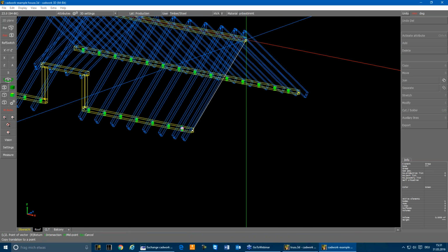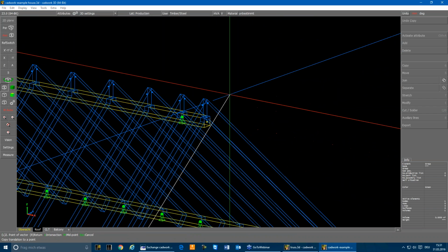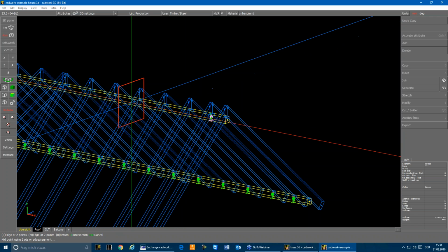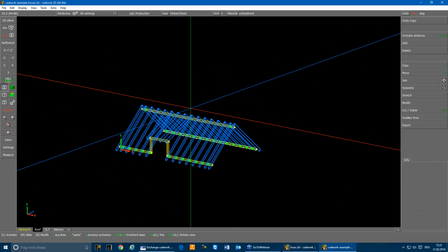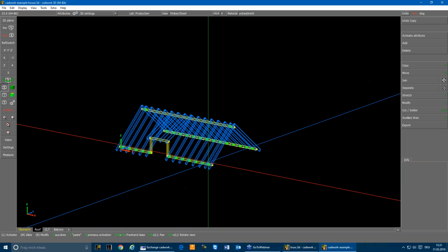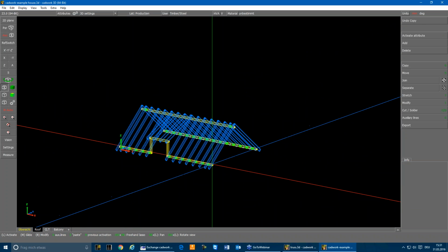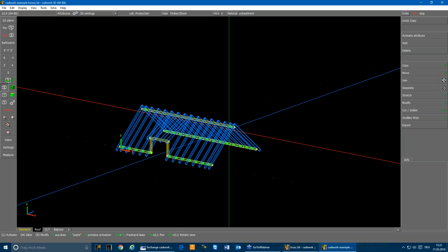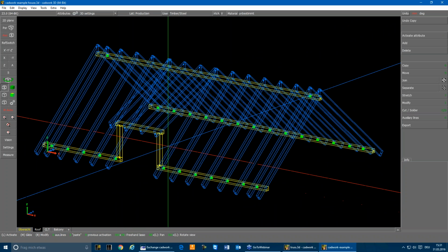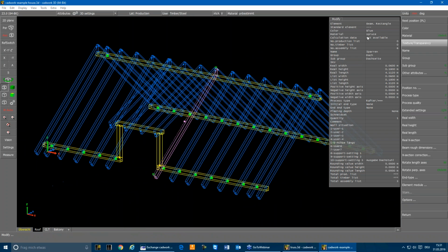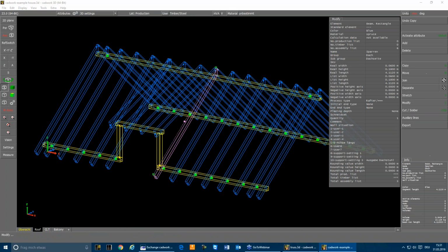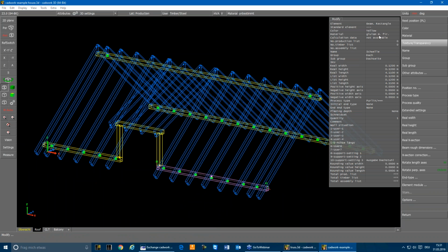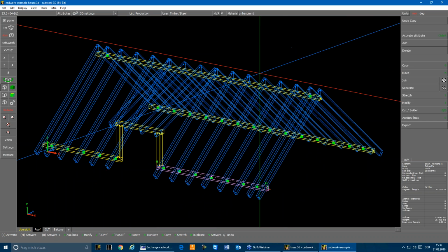So it means now we will put it from here to here to have a support in the ridge beam as well. Copy it to the other side, to the midpoint of this ridge beam, and we do have all the supports we need. So by switching off the auxiliary elements, now we have a model which looks like this. This is now including the rafter with, for example, material spruce, and the purlins and posts with the material glulam as well, like we had before.